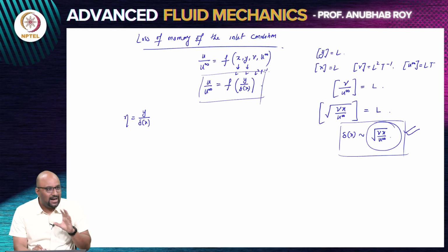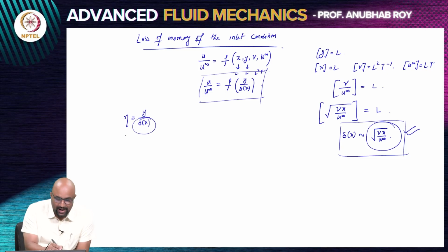See, the whole idea of boundary layer theory is that there is a very thin region close to a surface where viscous effects are important. Now, if you want to look at the problem at the scale of the boundary layer, it's like taking a magnifying glass which only zooms in one direction. It doesn't zoom in the flow direction, it only zooms along the y direction. So, this is that zooming factor.